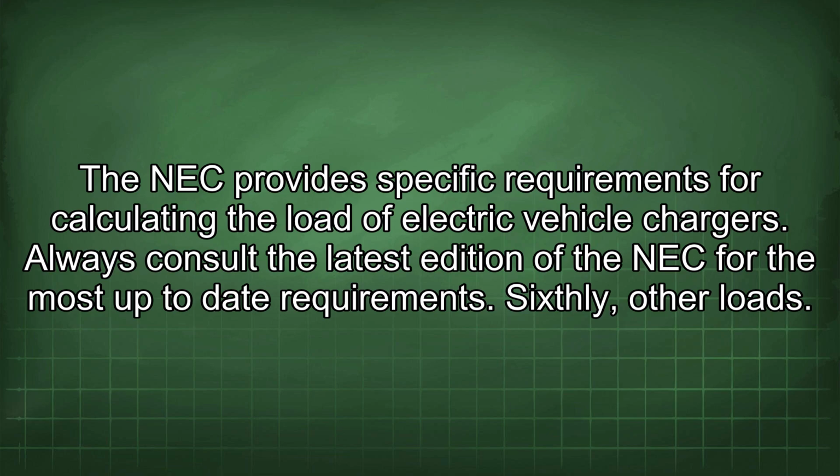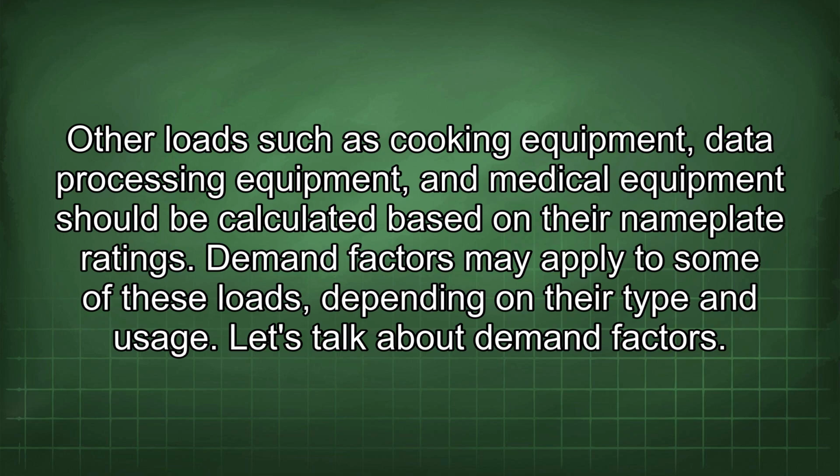Sixthly, other loads. Other loads such as cooking equipment, data processing equipment, and medical equipment should be calculated based on their nameplate ratings. Demand factors may apply to some of these loads depending on their type and usage.